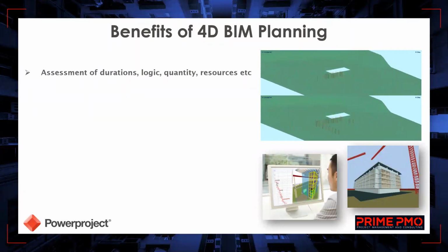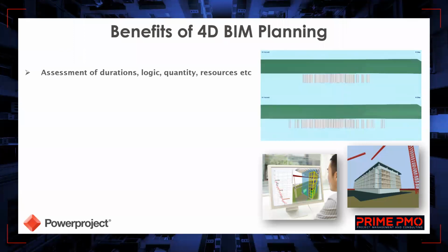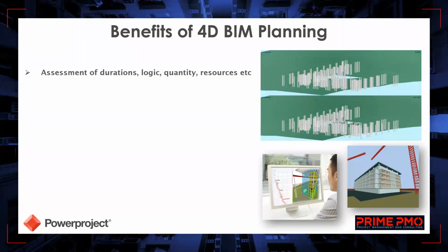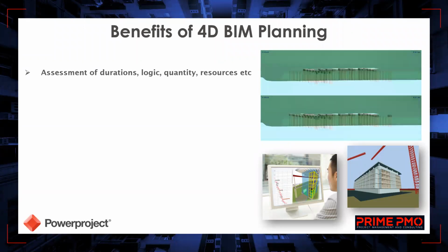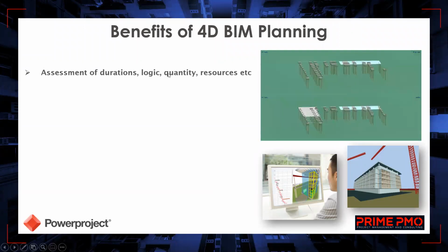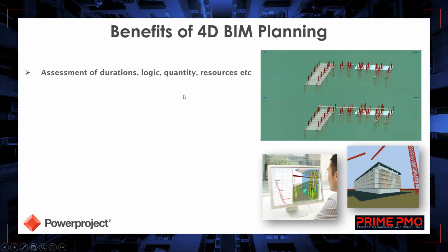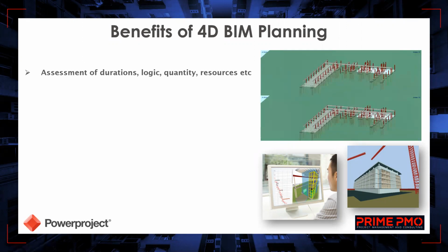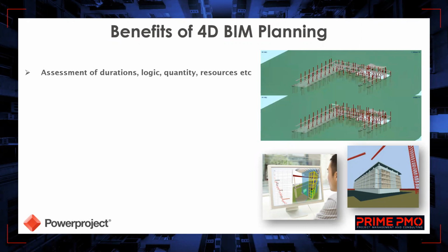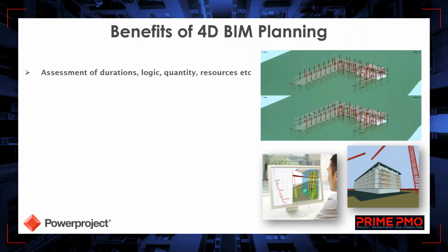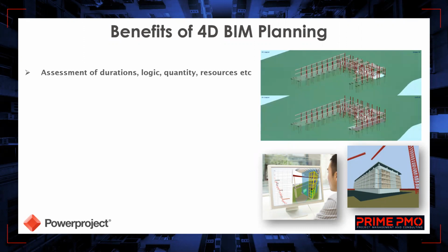Another advantage is the assessment of durations, because as I said, the BIM model has information. What kind of information? The location information of any product, the quantity information, the material information, and we can use this information in our schedule to estimate the activity durations, and we can have more realistic construction deadlines.